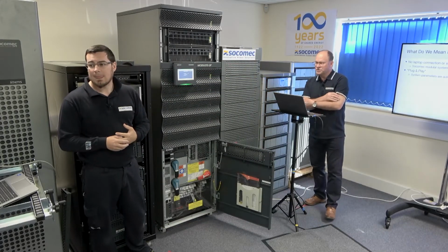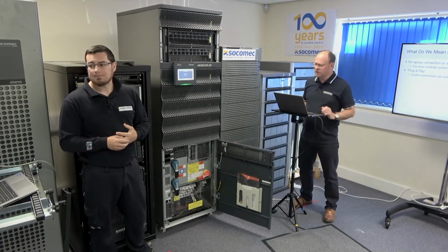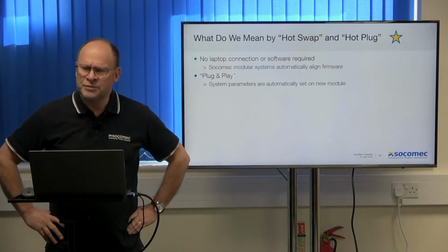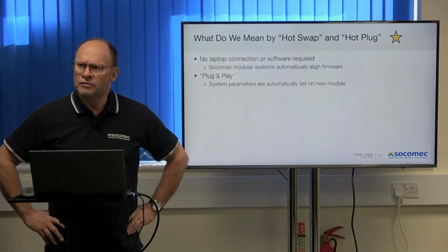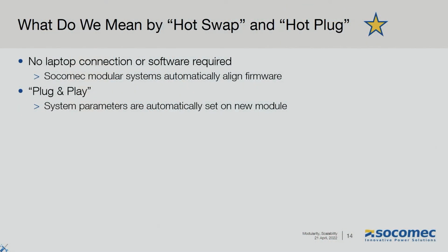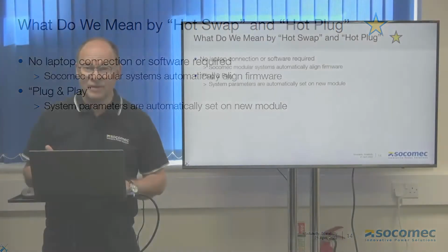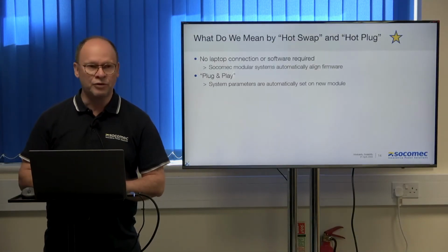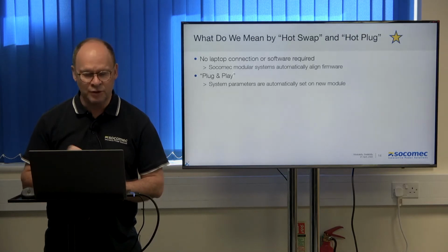Okay, yeah, this is a really key thing actually. We mentioned that it updates the firmware of the module. It aligns it with the system firmware. The reason we do that is because the system firmware is, A, working, and B, it's what's been approved by the end user. So that's why we do it that way around.